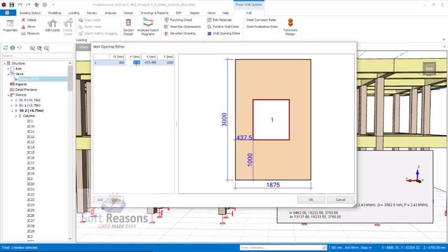So you now look at the height of it, okay, which is the extent, this x. You can see 3437.5, okay. Then the y is the 100, so the y is going to start from 200. All right, just like this. Then the height is going to take 2100, which is the headroom of a normal door, just like this. Okay, so you need to centralize this.